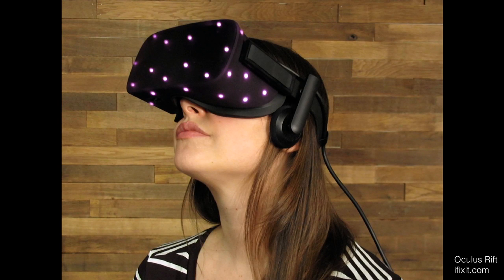So if you look at something like Oculus Rift, positional tracking is done with a little camera that works in IR, and there's a whole bunch of near IR LEDs on the headset that the camera will track. We don't usually see this because we're not sensitive to near IR, but the camera will see them, and they're arranged in a pre-configured set in a 3D configuration on this headset. So this is what the Rift looks like if you had a near IR camera, or if you're a mantis shrimp or some other animal that can actually see near IR.